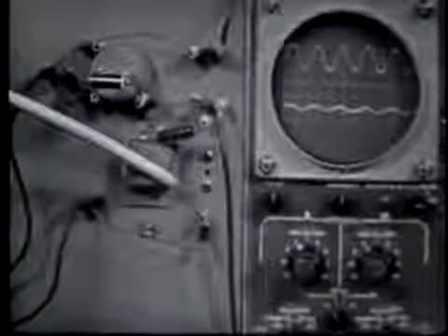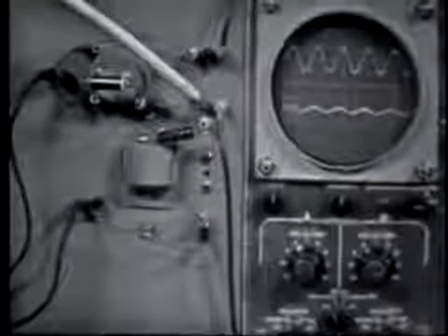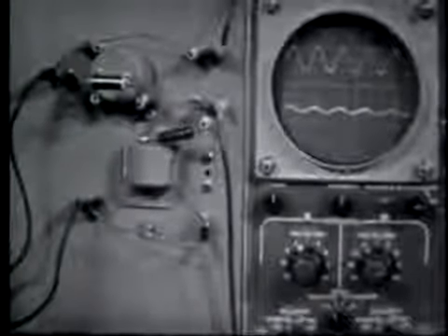Now we have our demo hooked up as a simple L section band reject filter, a parallel tank in the series position, our little shorting wire, and a series tank in the shunt position composed of this capacitor in series with this inductor, and of course the other side of the inductor going to ground, and our output is taken across our shunt component. Now we've said that the T and pi section filters provide improved filtering action over the simple L section. What do we mean by improved filtering action?